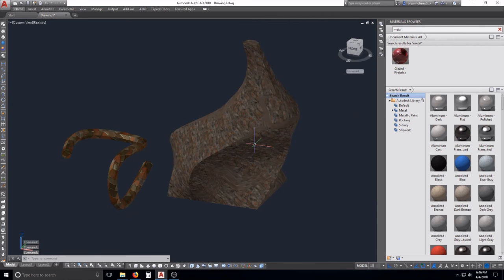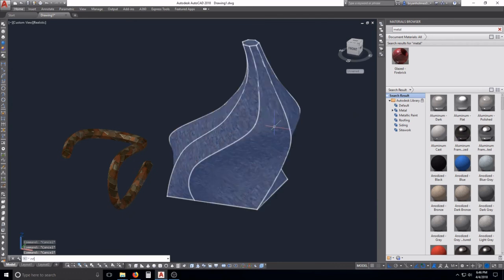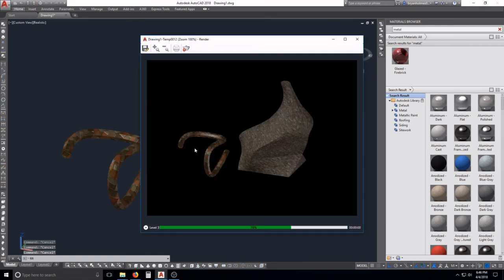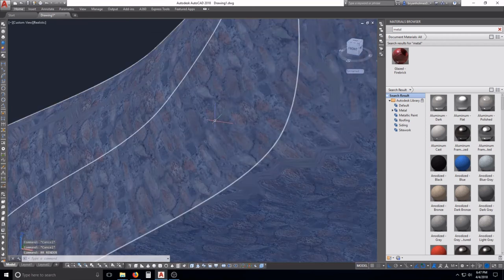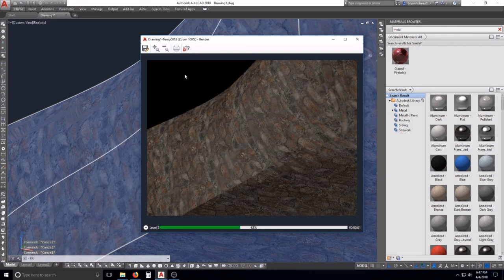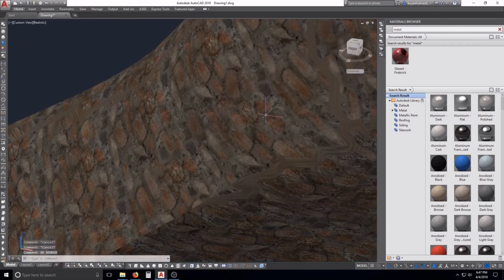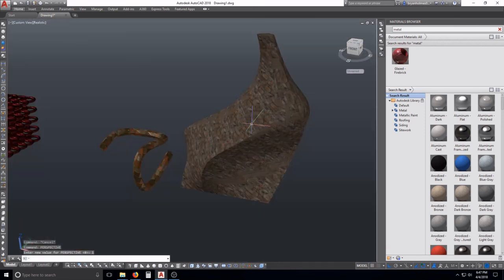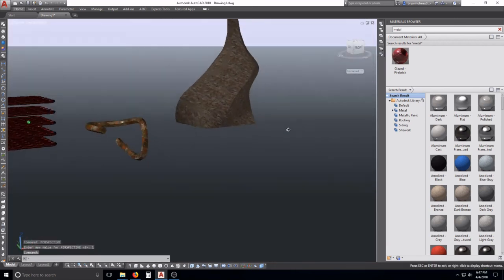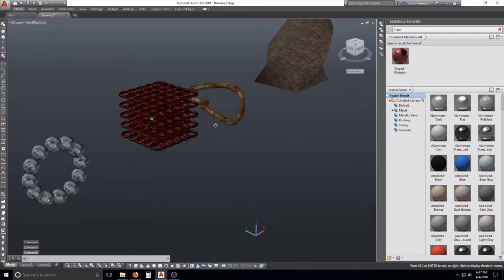So if we rendered this guy, and we're not going to add lights to it, but we're just going to render it just to see what it looks like. RR enter. That was one I did before, messing with. So you can kind of see what it looks like. And we're a little bit big, so if we zoom in a little bit, RR enter. So you can kind of see. And if you type in PERSP, and then you turn it on with 1, just zoom out. Usually it has some crazy weird zoom factor to it.